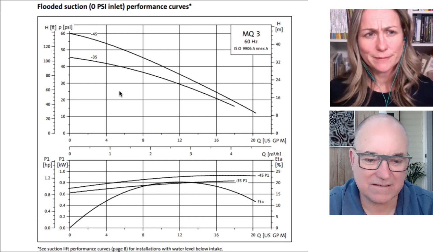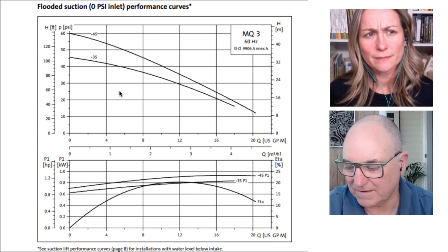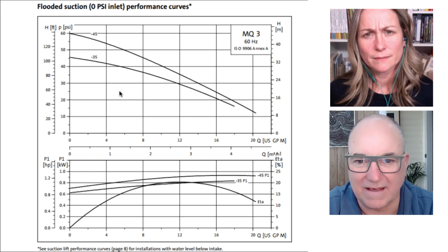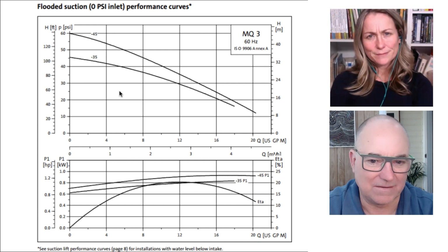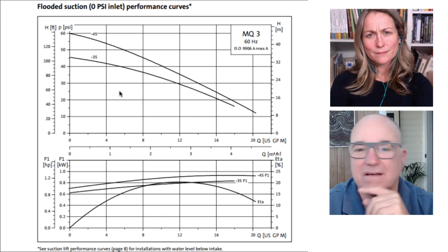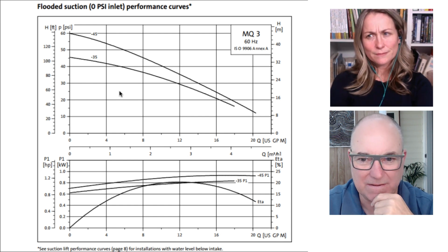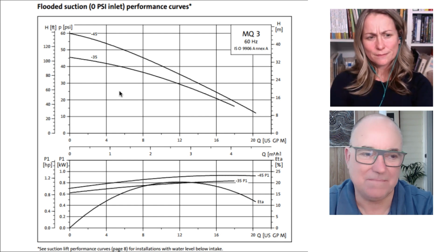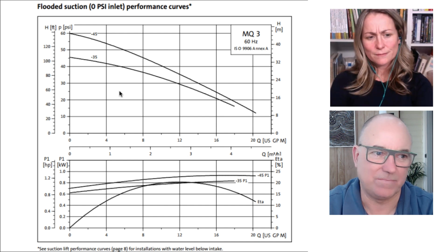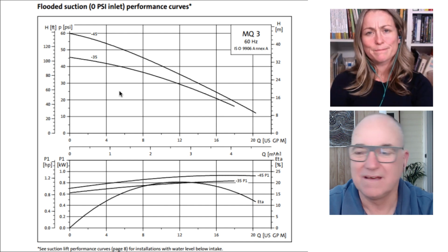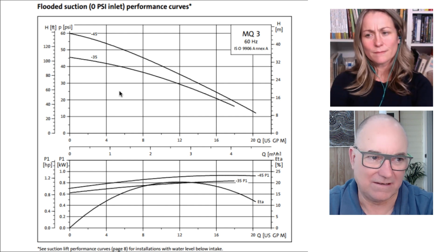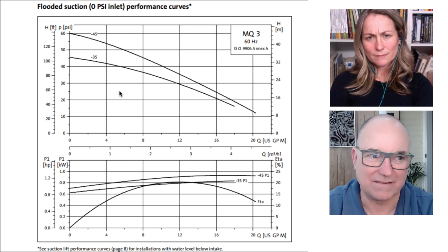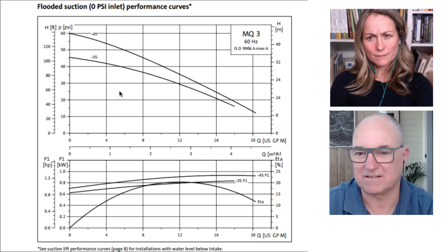There's 2 answers to this. If it's just someone wanting to put a pump in their household, to know about this is vitally important, so it avoids the homeowner or the designer getting this quite wrong. Don't accept someone making an argument to you that if you get it too big, it doesn't matter because it's conservative, because you'll find that'll create massively counterproductive outcomes. You want a pump that's close to what you need. Dramatically oversized is not a good design,